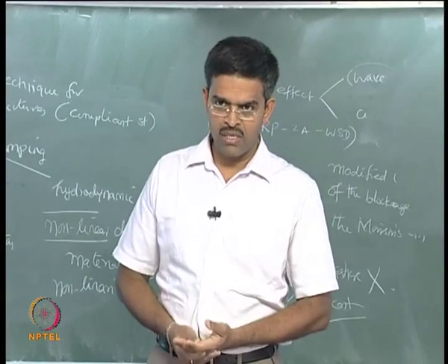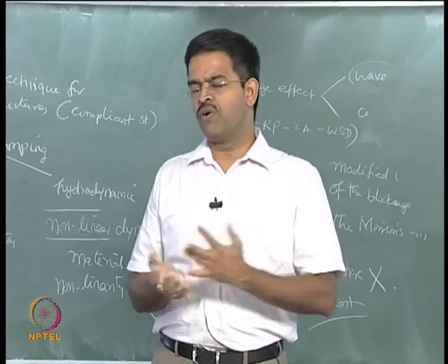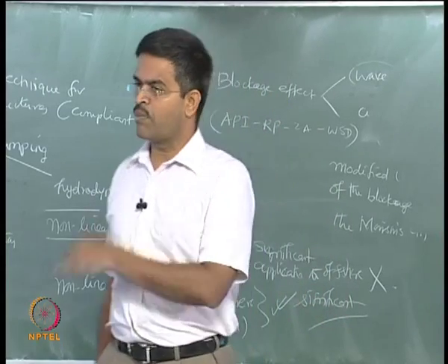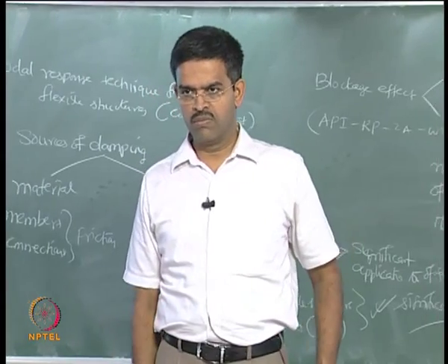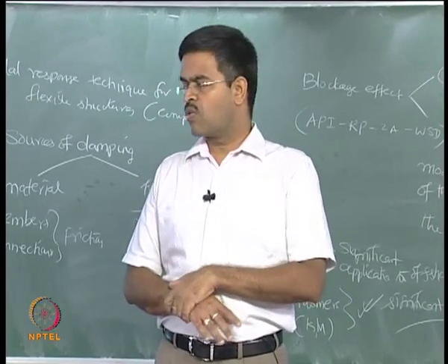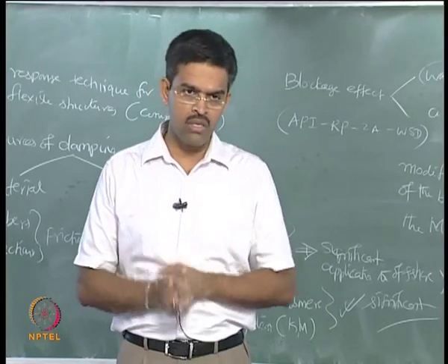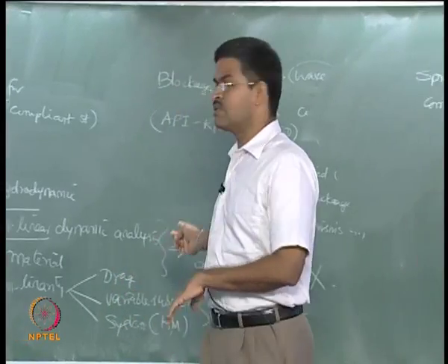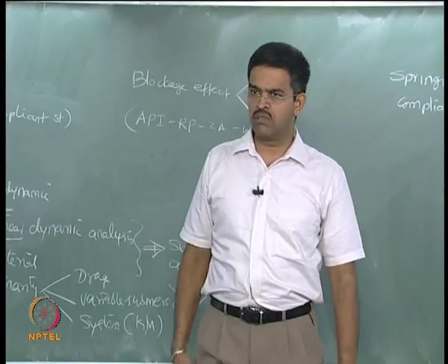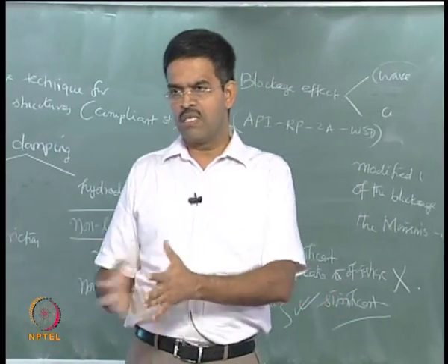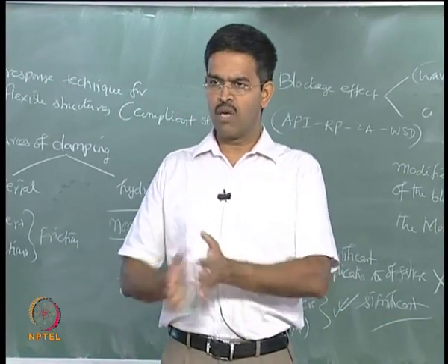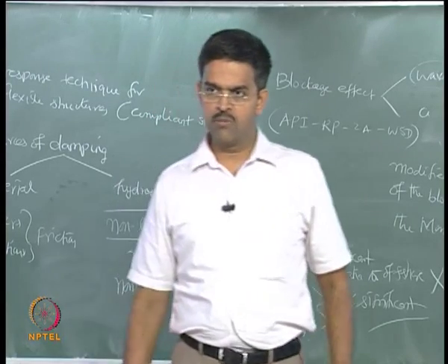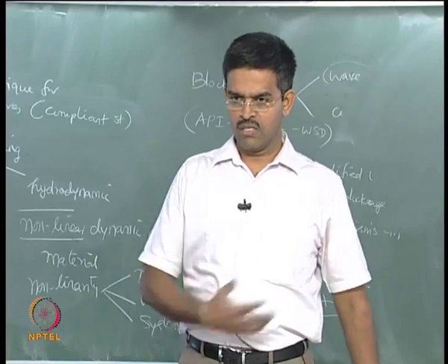How to quantify this depends upon how you arrive at f of t on the right hand side of the equation of motion, which we will keep on seeing from now onwards in all example problems in the next modules or in the next lectures in the same module. So qualitatively we have understood how FSI is important, quantitatively how they are carried out in terms of different non-linearities present in the system, how you solve the equation of motion, and how the system would be designed so that the frequency of the system is kept off band from the wave frequency, and why the responses are still important in specific degrees of freedom only, which we will discuss in different examples.